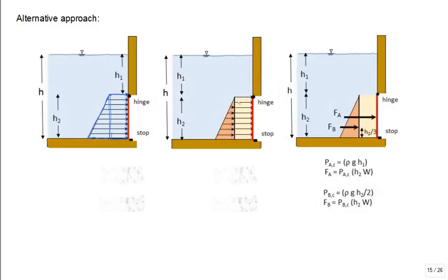I'll replace the rectangular load by a resultant force A, which is right in the middle. And I'll take the triangular load, force B, which acts at 1/3 up. Then I'll put them into an equivalent force if I want a separate force, or I'll just keep two forces due to hydrostatics in my calculations.